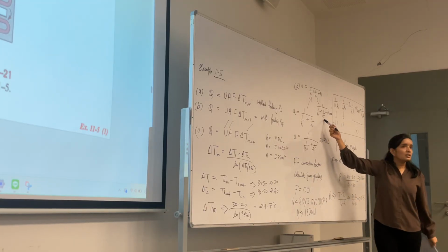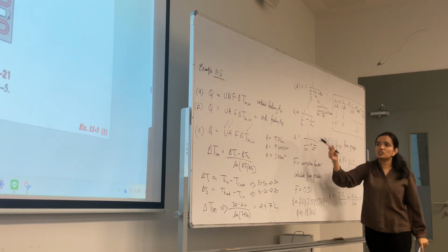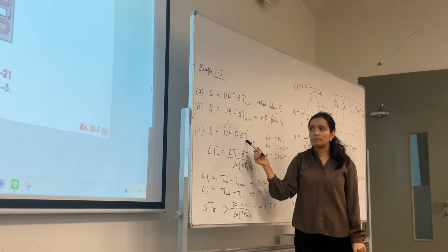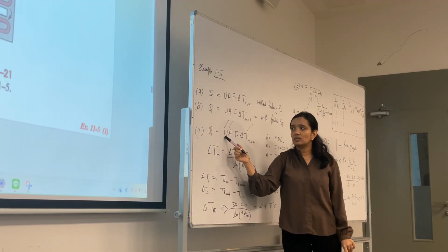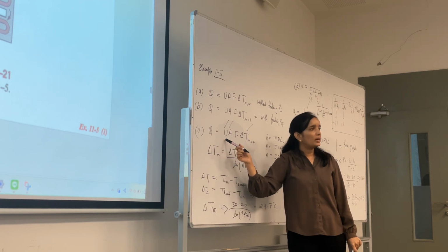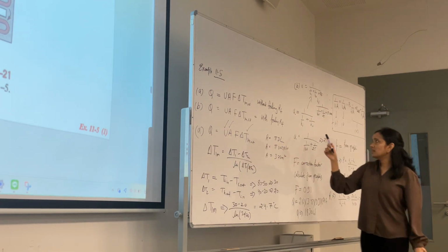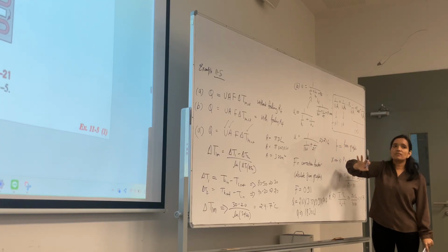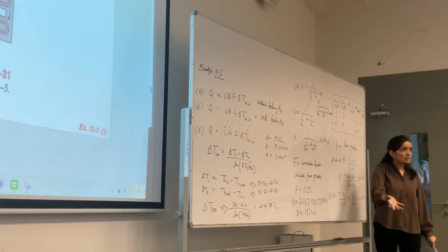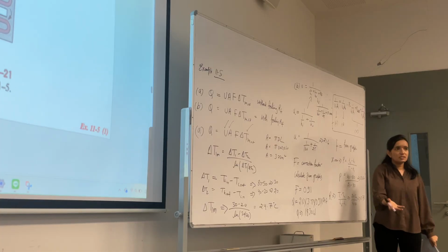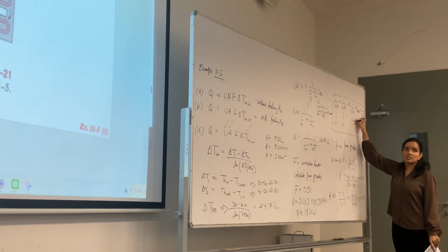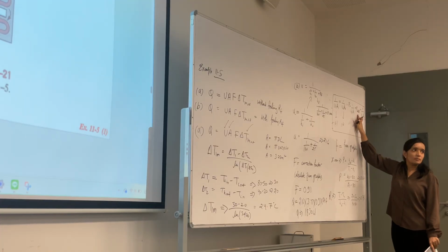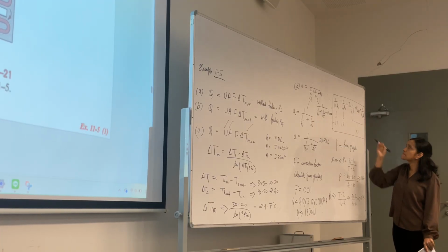This will only be the difference. So only U will change. Only this will change. This stays same, this stays same, this stays same. Only this will change for the B part, because we have to add a fouling factor. And we add the fouling factor like this. Fouling factor is a type of resistance, so we add a resistance here. There is a plus, there is a wall. This is 0 because this is the wall.